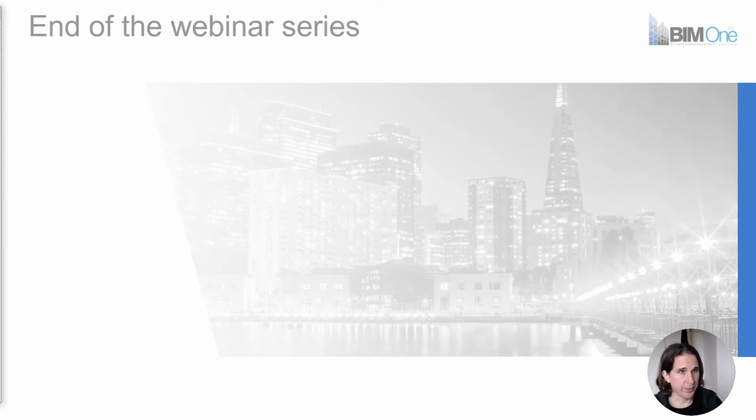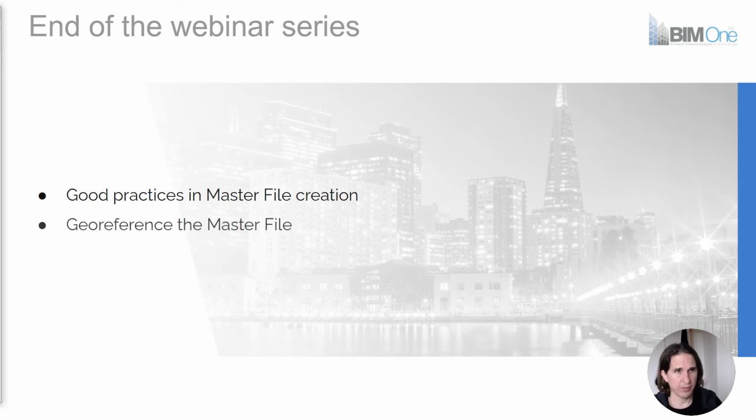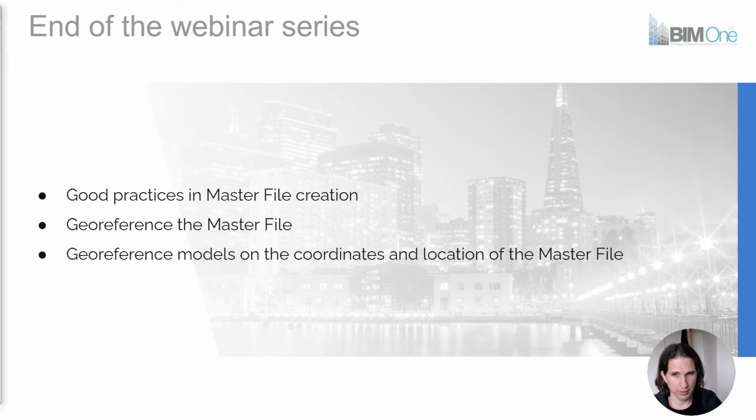That's the end of the webinar for today. So we went through the good practices of creation of a master file, and then we geo-reference it properly. And we also geo-reference models on the coordinates and location of the master file. That concludes our webinar series, and thank you for attending.